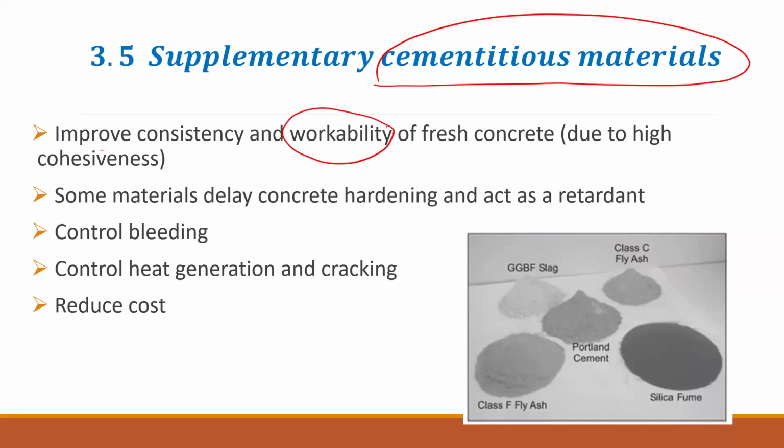Workability is how easy it is to mix the concrete mix. Workability of concrete depends on many things, on the cement and on the aggregates. When we do the concrete mix design, I will explain more about it. When you have rounded particles of aggregates, it is easy to mix. But when you have irregular particles of aggregates, then it is hard to mix. Also, if you add more water, it is easy to mix, so we call it more workable. And if you have less water, then it is hard for you to mix the concrete.